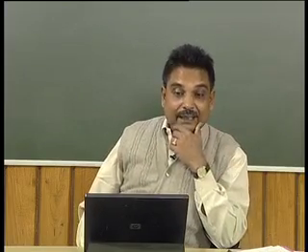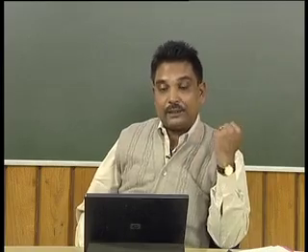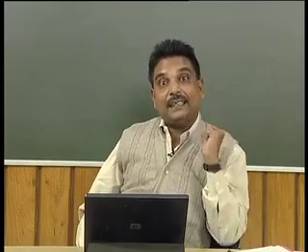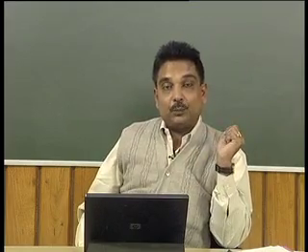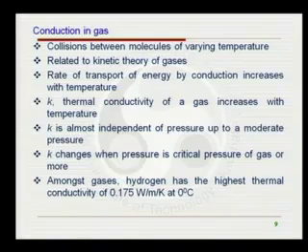Now, if I say the typical gas, say hydrogen, hydrogen has the highest thermal conductivity among the gases, and its value is 0.175 watt per meter per Kelvin at 0 degree centigrade. Because we have told that thermal conductivity could be a function of temperature, it may be a weak function, it may be a strong function, but when we talk about the thermal conductivity, we should tell at what temperature we are telling about the thermal conductivity.